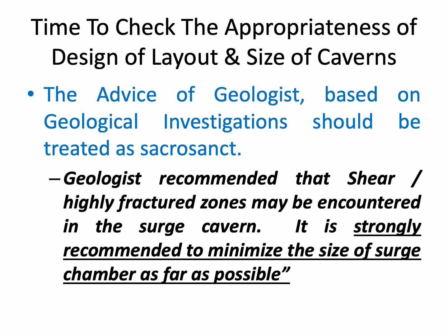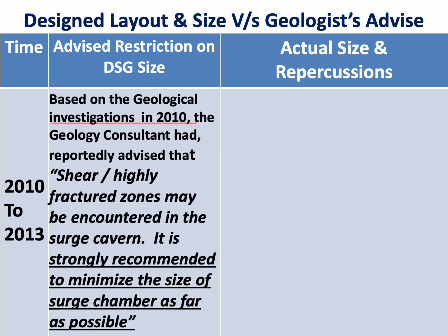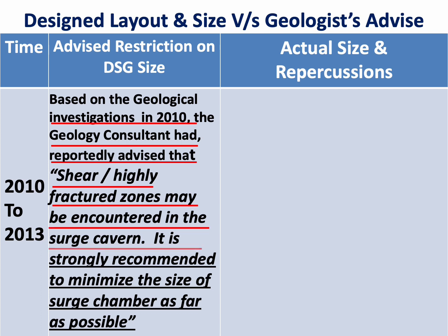But what was the designed layout and size versus geologists' advice? Let us see. Between 2010 to 2013, based on geological investigations in 2010, the geology consultant had reportedly advised that shear/highly fractured zones may be encountered in the surge cavern. It is strongly recommended to minimize the size of the surge chamber as far as possible.